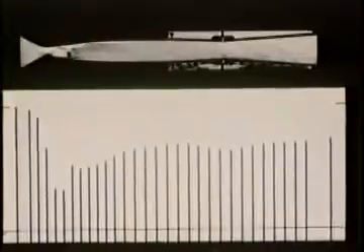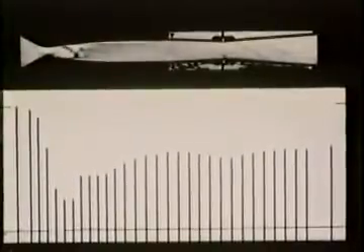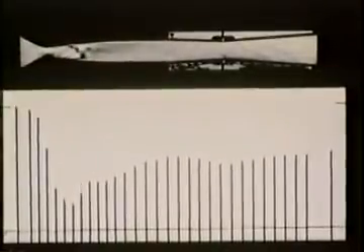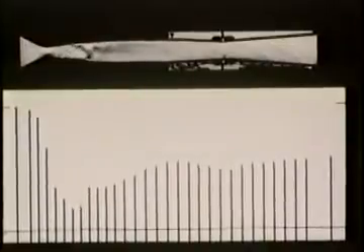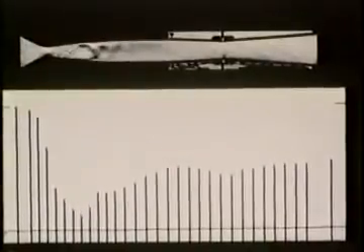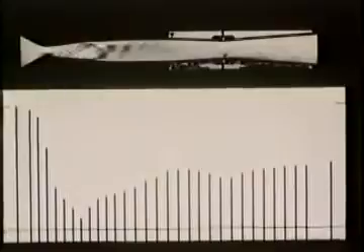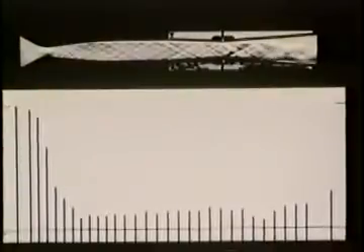Suddenly, the shock wave jumps into the subsonic diffuser. We say that the channel is now started, or running, and that the original shock wave has been swallowed by the second throat. The wave pattern ahead of the second throat and the pressure distribution show that the flow is supersonic all the way from the first throat to the terminal shock wave.